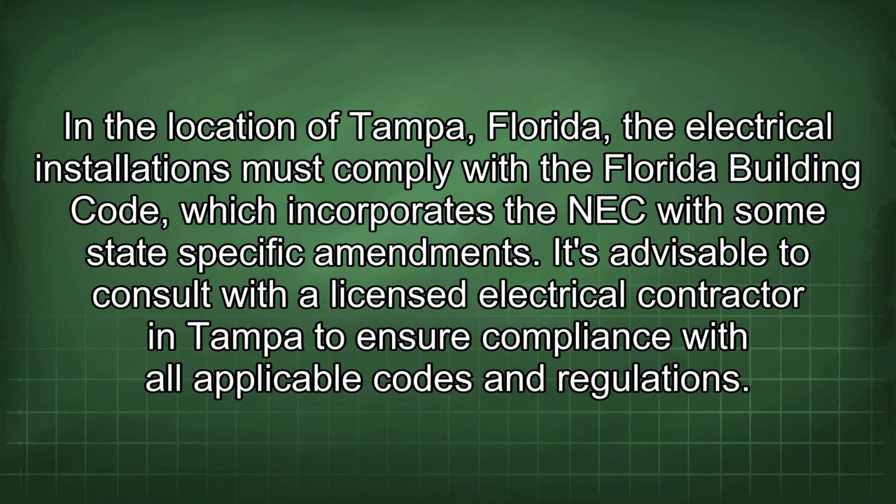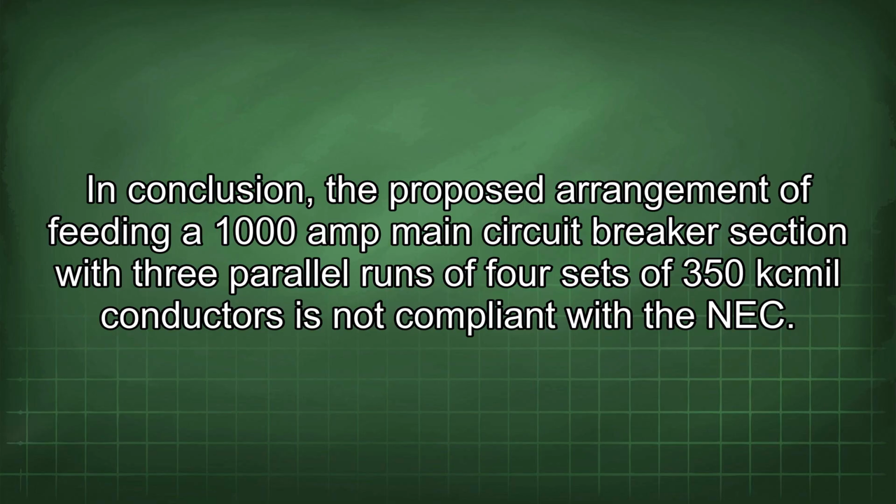In a location like Tampa, Florida, the electrical installations must comply with the Florida Building Code, which incorporates the NEC with some state-specific amendments. It's advisable to consult with a licensed electrical contractor in Tampa to ensure compliance with all applicable codes and regulations. In conclusion, the proposed arrangement of feeding a 1000 amp main circuit breaker section with 3 parallel runs of 4 sets of 350 kcmil conductors is not compliant with the NEC.